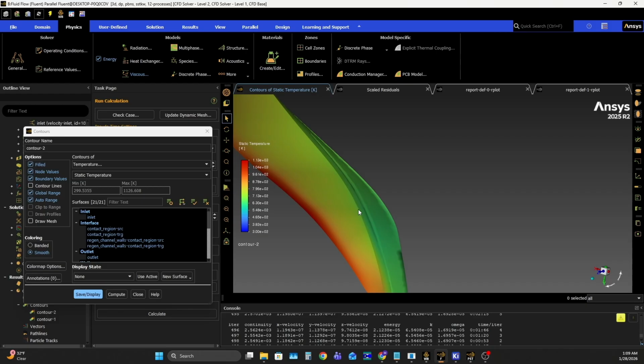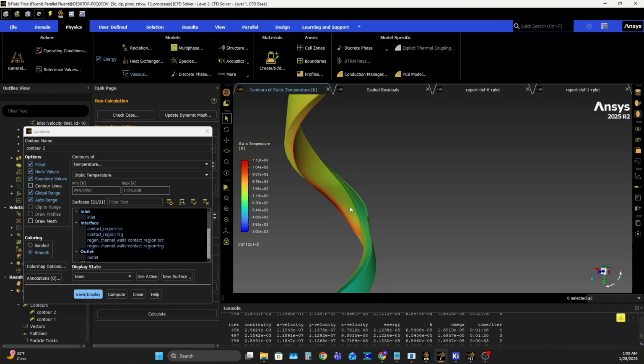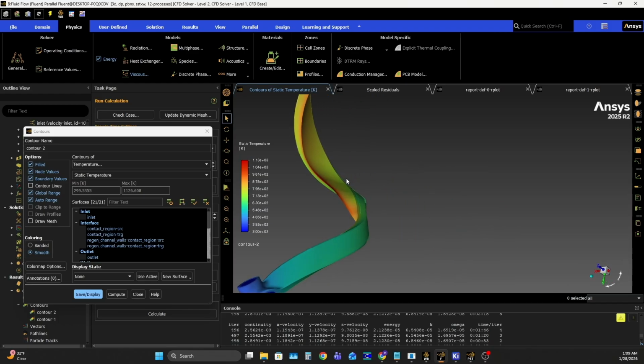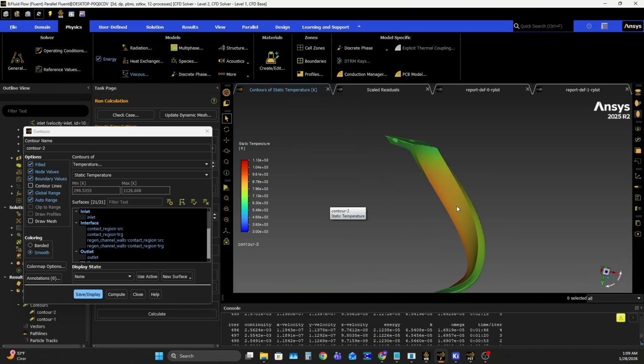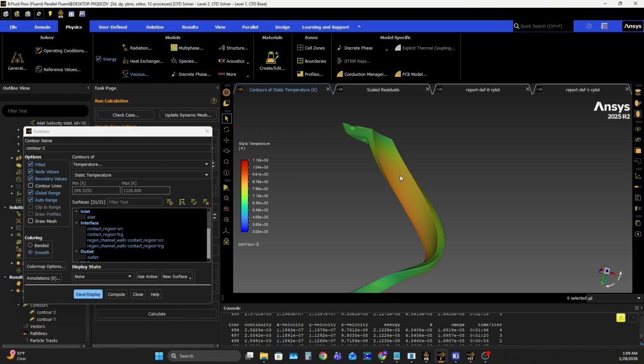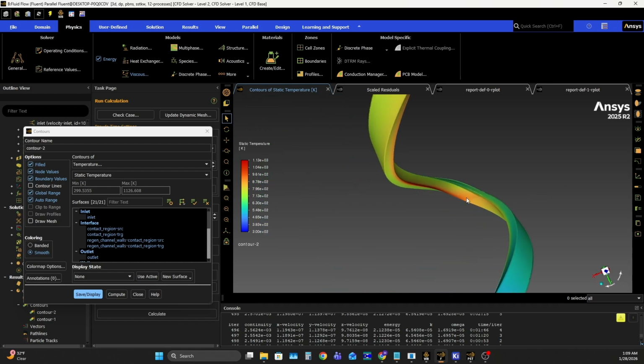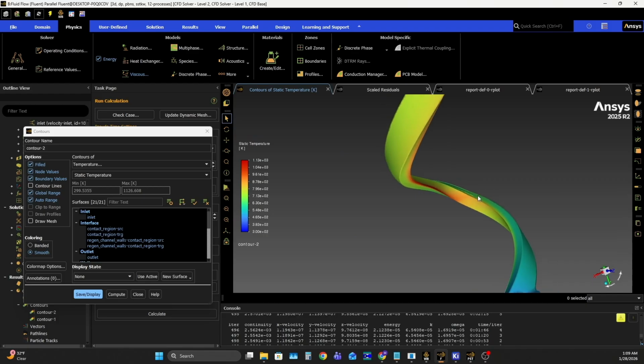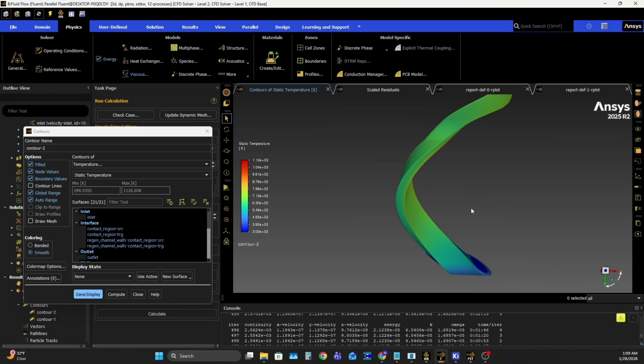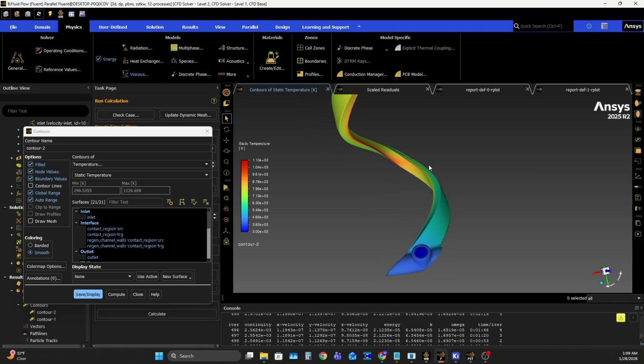We can also see this side is a little bit cooler for the exact opposite reason. This side's probably a little bit closer to the closest regen channel being modeled. But that's okay because we really just care about the average across here. And we can see that for most of the chamber, it stays roughly the same temperature. We do see a little spike at the throat, but it's not unreasonable. And then obviously the nozzle is perfectly fine.